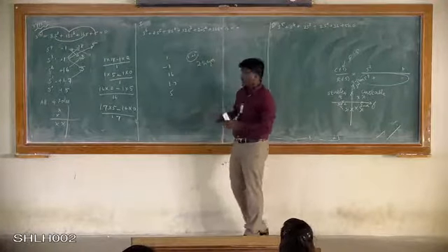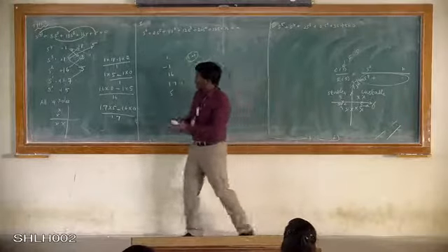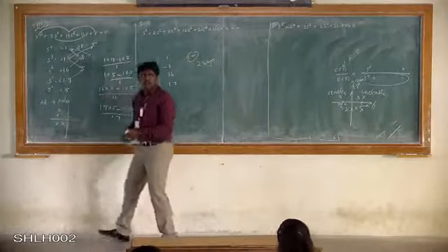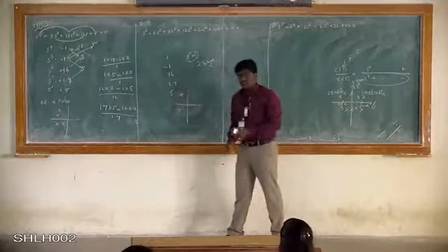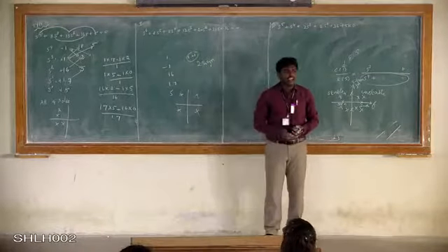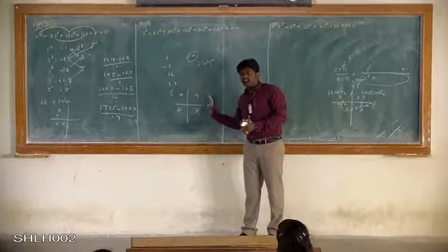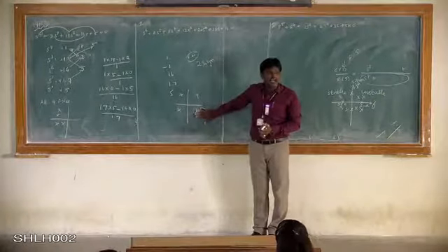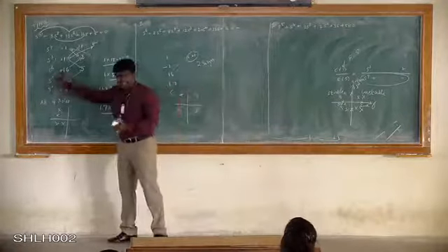If you have got 2 sign changes, you will have to write it like it is a fourth order system. So 2 poles are lying on the left half of the S-plane and the remaining 2 poles are lying on the right half of the S-plane, right? So you have got poles lying on the right side also. Then the system is unstable. Got it? Just by solving it using the Routh table, right?